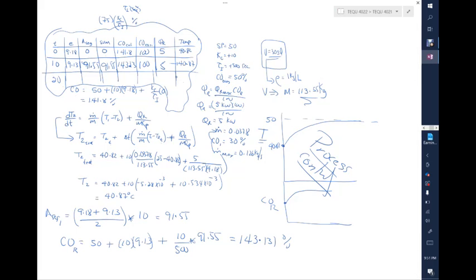We did steady state. We know that the system auto-regulates, and that's what makes us sure that yes, we can use a PI controller on this system because it auto-regulates. If the system does not auto-regulate, don't try a PI, try a proportional controller. So for now, we move to Excel. Wait for that.